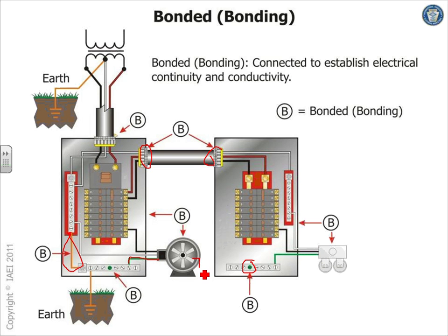Yeah, so you drive a ground rod here, and you tie the ground rod to the equipment grounding conductor. They do it if you have a machine outdoors for lightning. They drive a ground rod right through it. But you're not tying the neutral to it. You're just tying the frame. You can have a ground rod everywhere you want, on every sub panel. There's no problem as long as you don't bond a neutral to it.